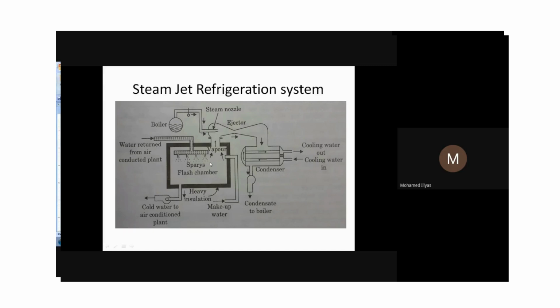So there is a decrease in the temperature of 2 to 5 degrees Celsius. For example, initially the temperature will reduce quickly around the 40 degrees Celsius, so it will come down to 35 degrees Celsius. So that is the advantage. Again, I am evaporating another 1 kg of water here. So the temperature will reduce to reach 30 degrees Celsius. But what is the disadvantage?